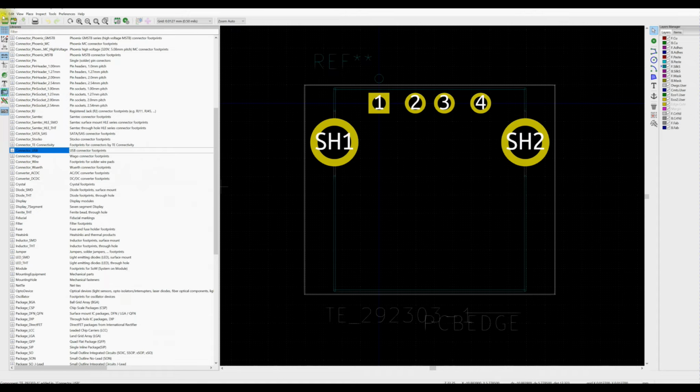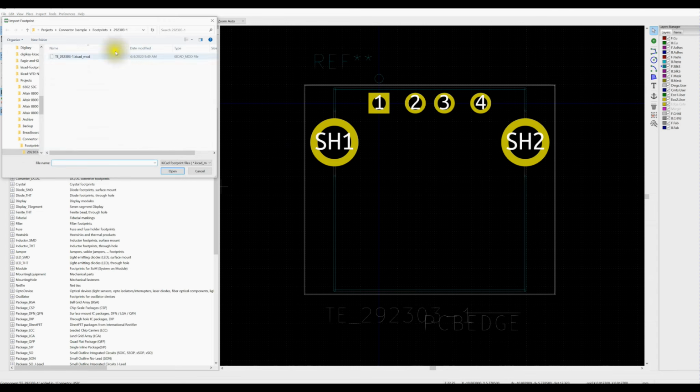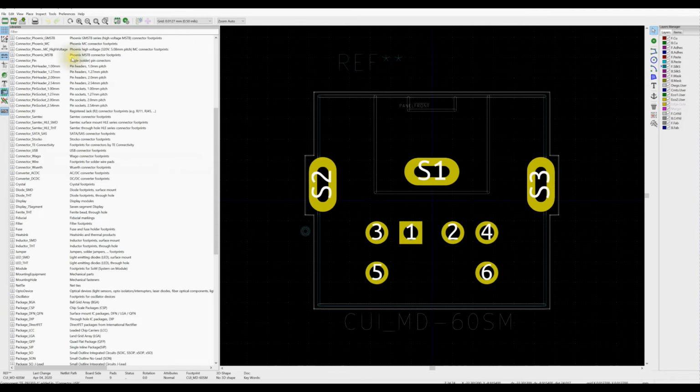Let's go ahead and import footprint from KiCad file. Let's go ahead and import the other one. We've got our footprint file. Yep, and that's the one for the PS2 connector. And I know, actually looking at this, that the numbers here are correct. I've dealt with this connector enough that this matches my expectations for what the pin numbers are, so that's a good sign.